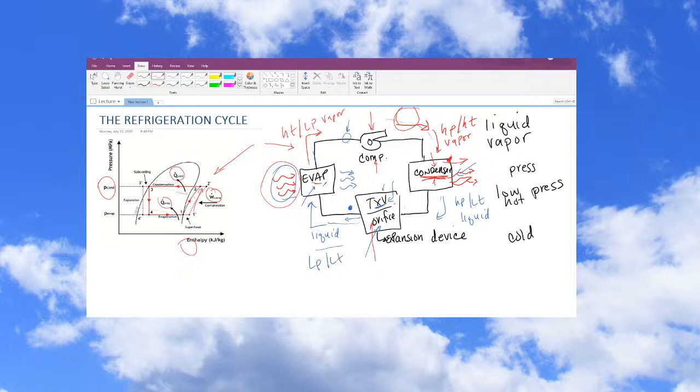We're adding work to the system, and that is done with the compressor. If you think about your car, that's attached to your crankshaft via a belt, and that's pulling energy directly out of the engine. So you're using horsepower from the engine to compress the air and travel up this pressure enthalpy graph. Typically these are pressure volume, but this one is focused around enthalpy because they're really going heavy on the Q, and they're going heavy on what happens during the phase change in this graph.